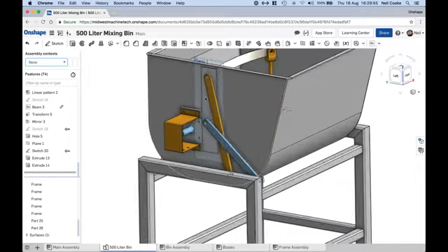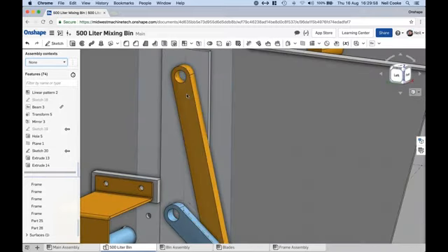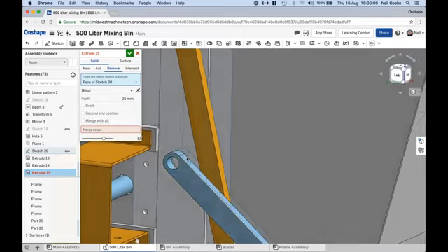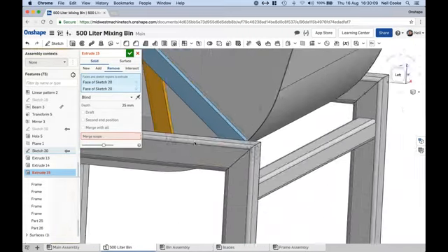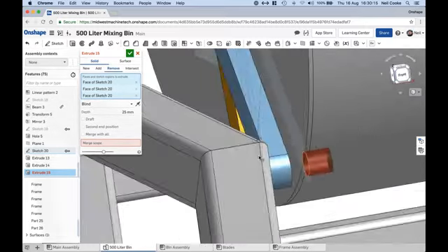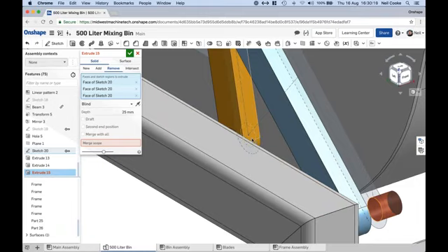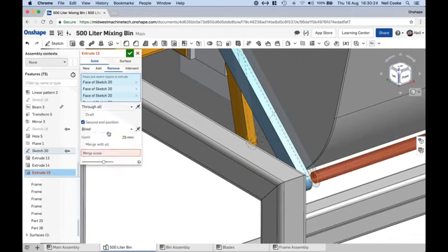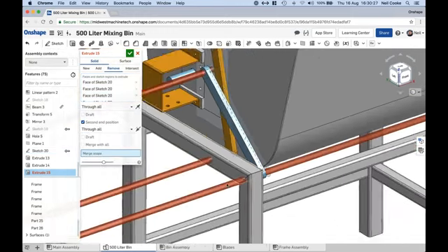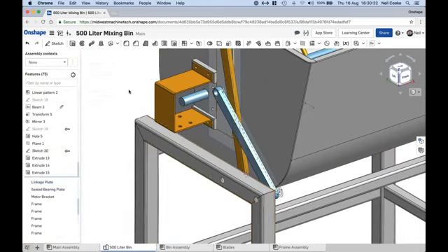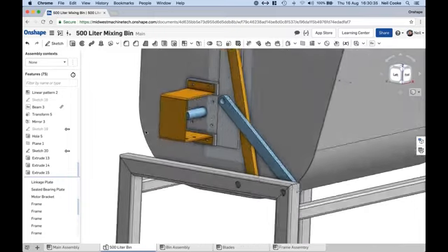Okay, last couple of changes we'll do here is just blow some holes through these other parts where these things will be positioned. So let's remove this profile, and select two more. This guy here and that guy there, and we're just going to do remove in both directions through all. Second version through all, and the two parts we're going to do it in is this part, and this mounting plate here. So that gives me then the assembly locations for this assembly.